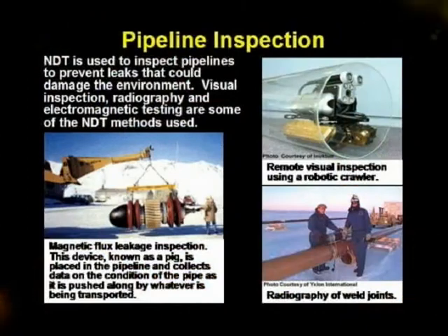Have you ever seen a buried pipeline which has ruptured? I have, and the damage can be extensive. Pipelines are routinely inspected using devices called PIGs, which contain ultrasonic or electromagnetic sensors to detect damage. I also worked on increasing the distance between acoustic emission sensors up to 1,000 feet for use on buried pipelines.